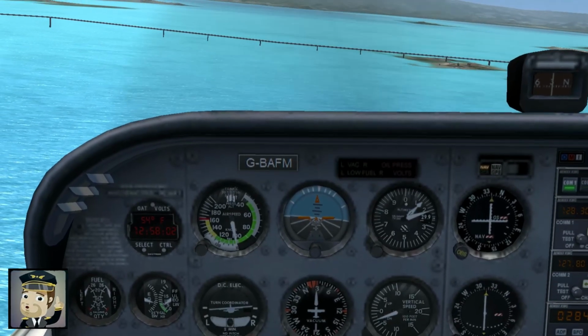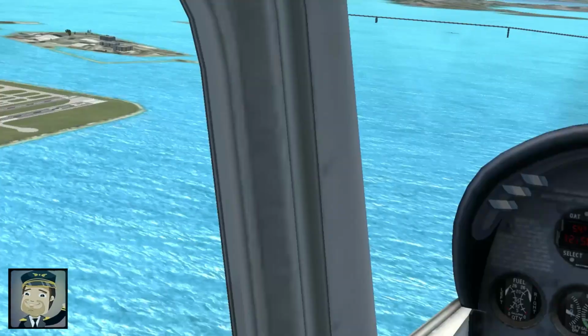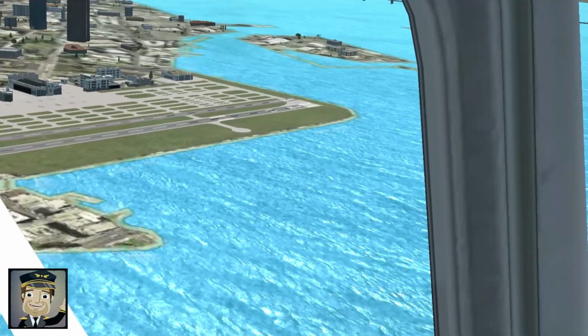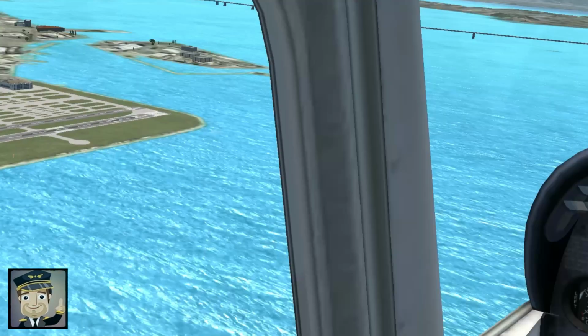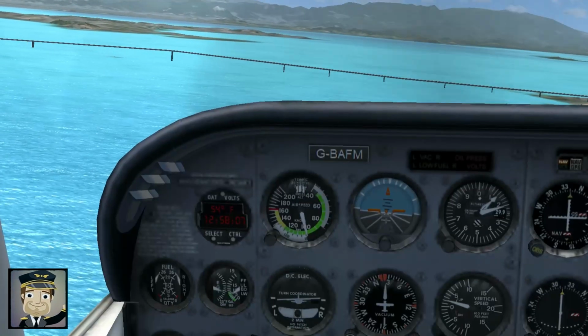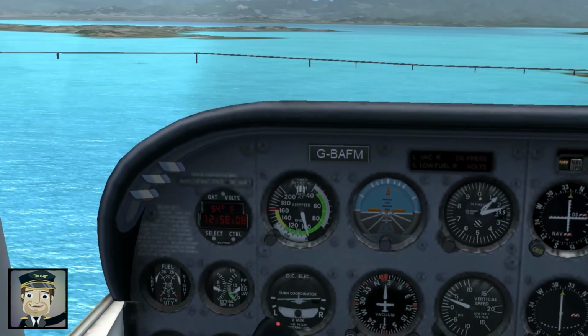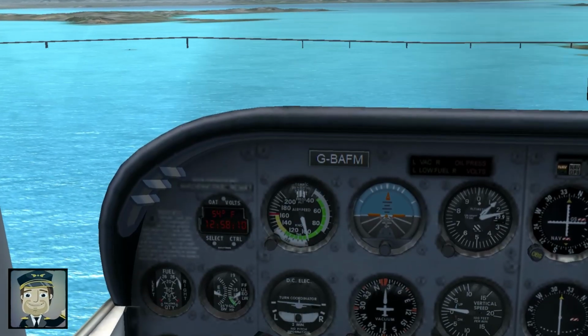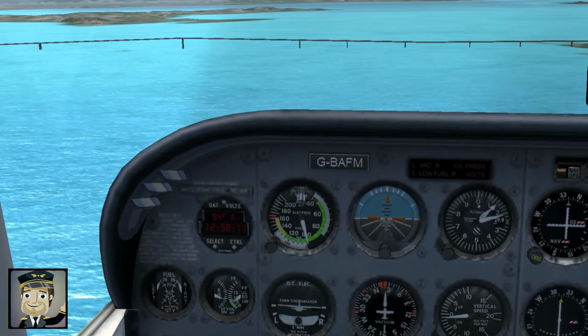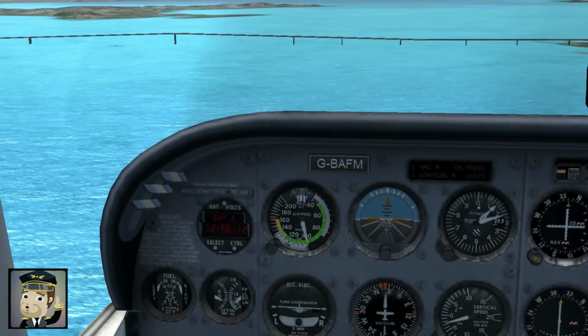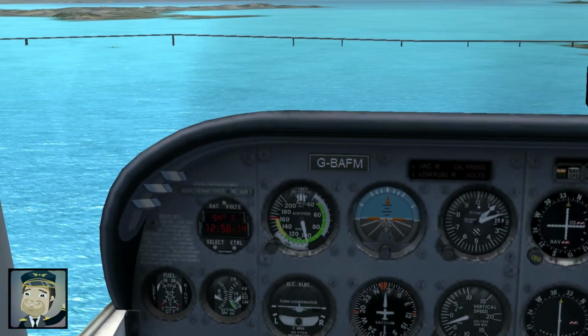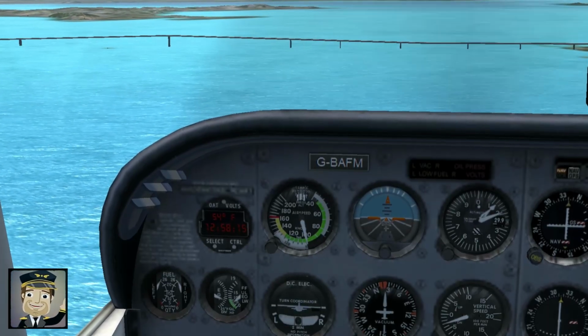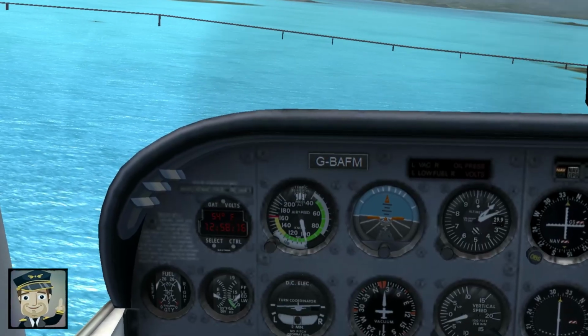The next major segment is the downwind leg. This is one of the longest and most important parts of the pattern. The aircraft now flies parallel to the runway once more, but in the opposite direction of landing and takeoff. From this position, the pilot sees the runway off the left wing, maintaining a consistent lateral distance, not too close, not too far, to ensure a stable base to final turn later. The downwind leg is a time of preparation.